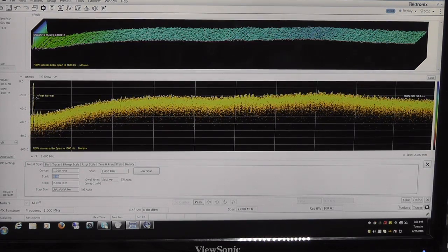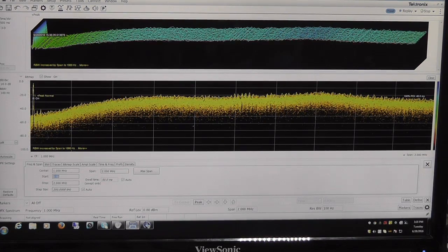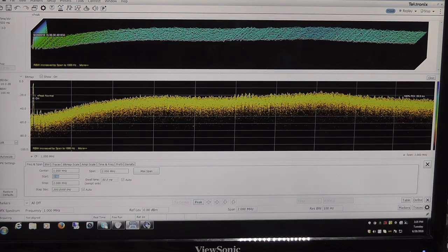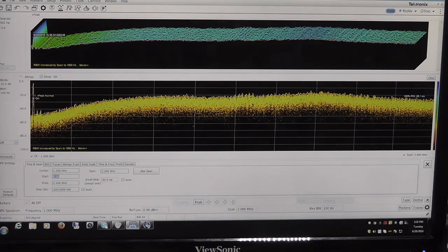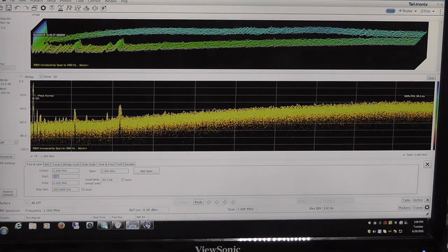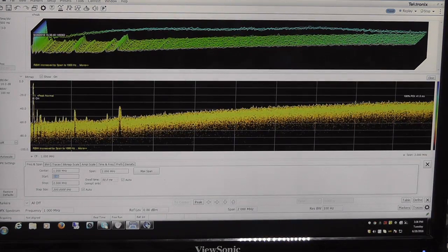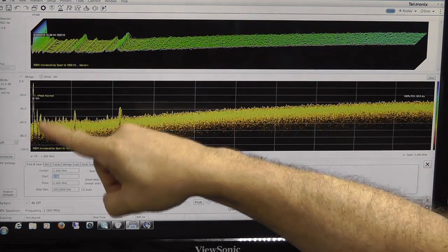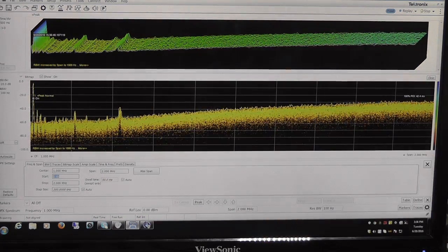Now let's watch what happens when I once again re-increase the sample frequency by a factor of 4 up to 20 megahertz. Boom, and down it goes. Again, we've uncovered our noise. And now the hump is shoved even further off to the right. And so our techniques have really bought us some signal to noise ratio here in a positive way.